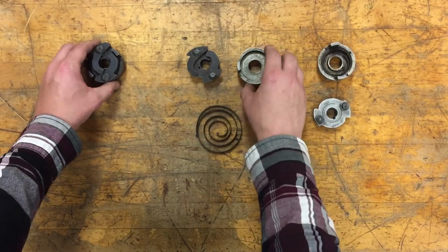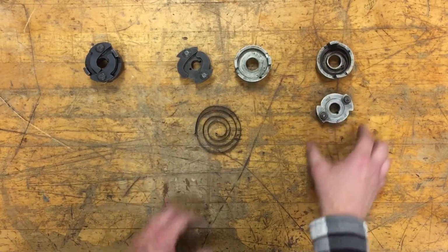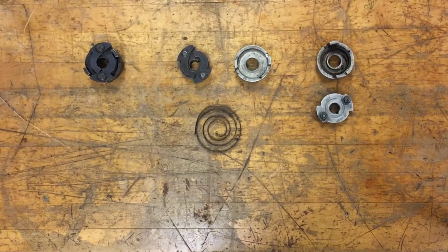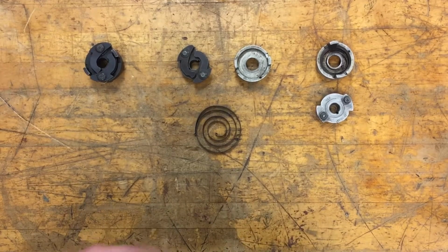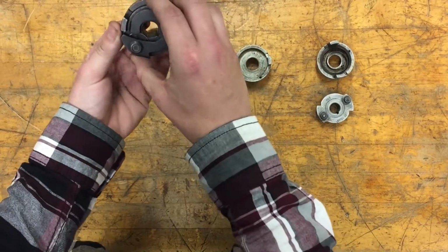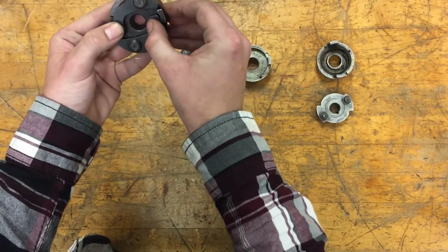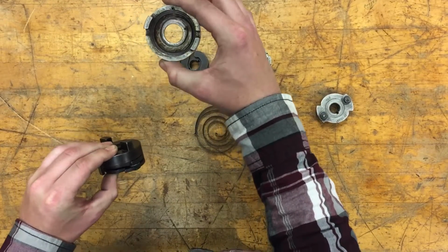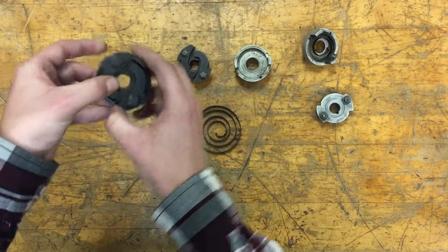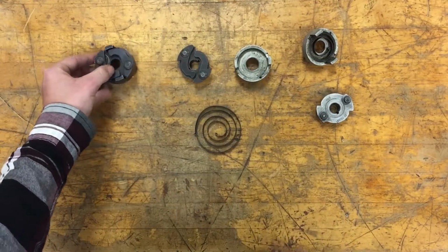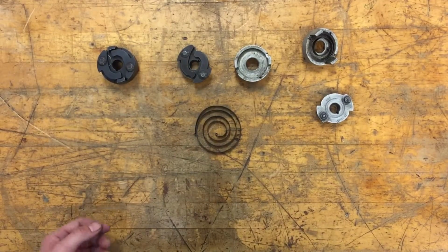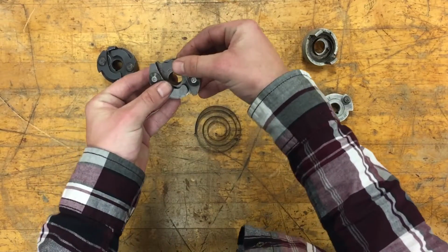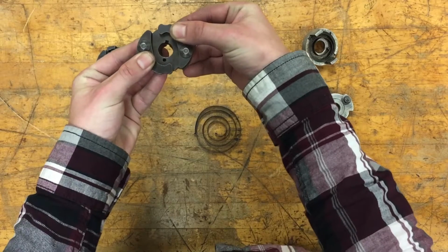So how this impulse coupling works is when the engine is being started by the starter, the camshaft is not turning fast enough for the Magneto to sustain a spark. These connect with the stop pins, which stops this spinning, and the continuous engine motion winds up the spring on the inside. And whenever it is wound up to the proper moment, it flings it forward so it spins fast enough to create a high energy spark. So when the Magneto reaches its coming in speed, the centrifugal force acts on the flyweights and pulls it out so it is no longer engaged.